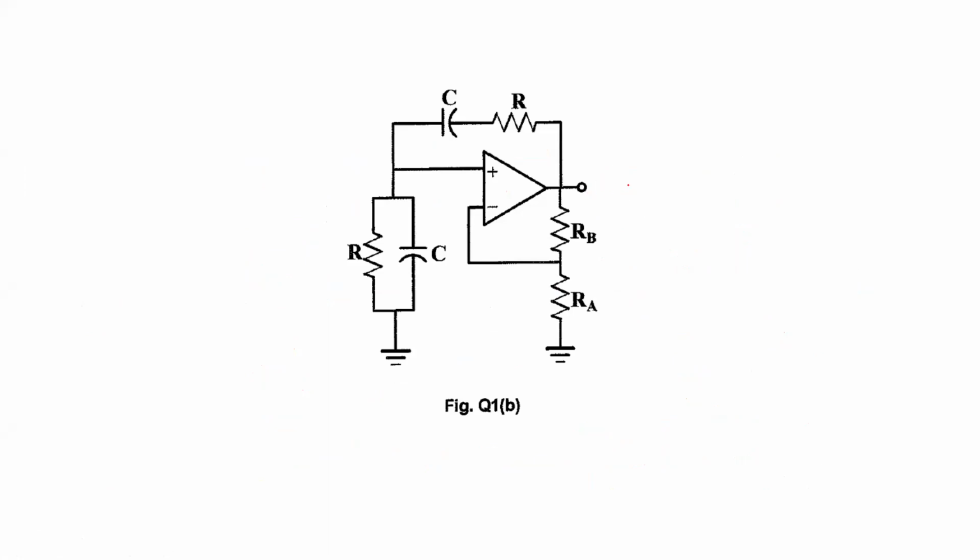Ideally, once you design this thing, you're supposed to get a nice sinusoid coming out. But because of the variation of the components, because of things like the op-amp and the components getting warm because they're carrying current and so on, what you find is that the amplitude here could start to deteriorate. And as you go along, it could die out. Or the other thing, it could start doing this and then start getting bigger.